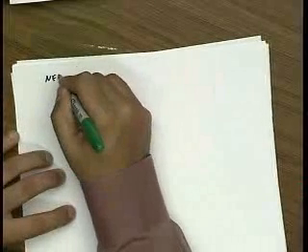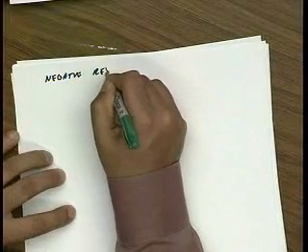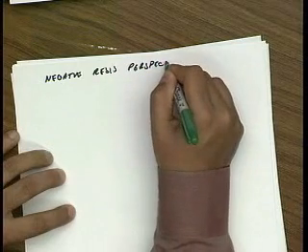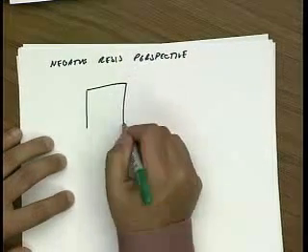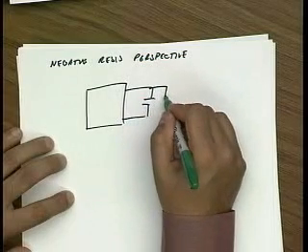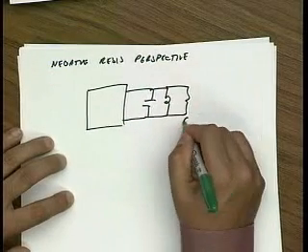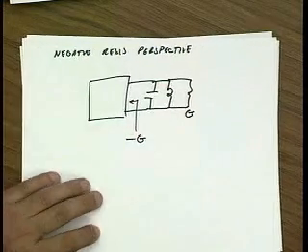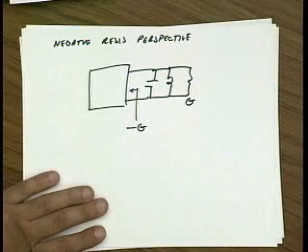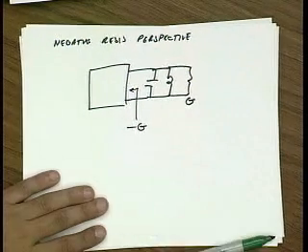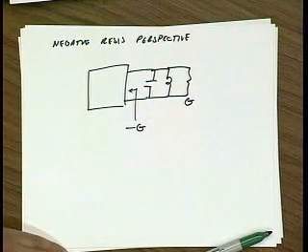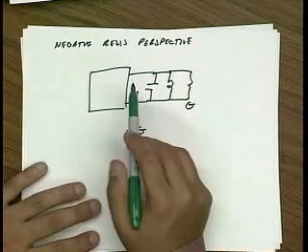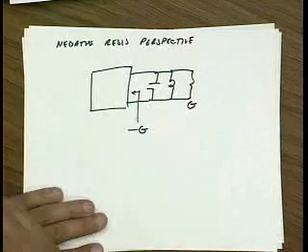So the question is, remember, that we can analyze our oscillator as a lossy LC tank, say with conductance G, and a circuit that somehow or another creates a conductance minus G. And this is consistent with our energy balance perspective, because in our energy balance perspective, if this circuit is supplying energy, that means it has negative resistance, right?